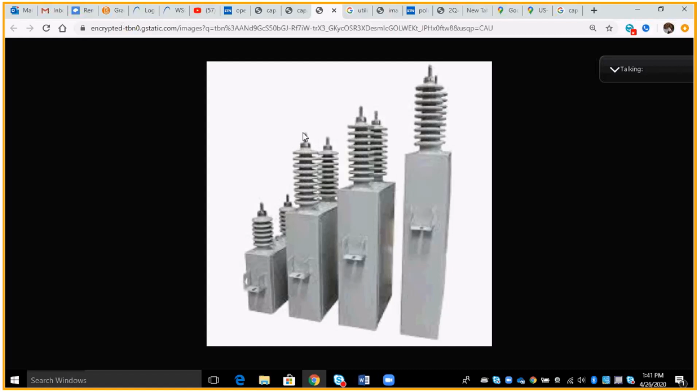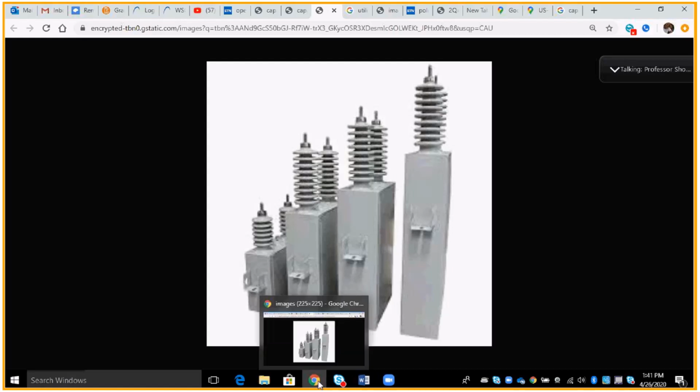I have seen situations where these have been in storage under lights, especially fluorescent lights, which will charge the unit. People have made contact and it has snapped them pretty hard. Think also, if you're transporting this on your truck or fleet, or the truck that brought it to you, and these are not shorted, you can get wind static. The wind blowing up against these can actually charge the unit and have an electrical charge inside the capacitor cells. They must be shorted at all times until you get ready to install them in place.